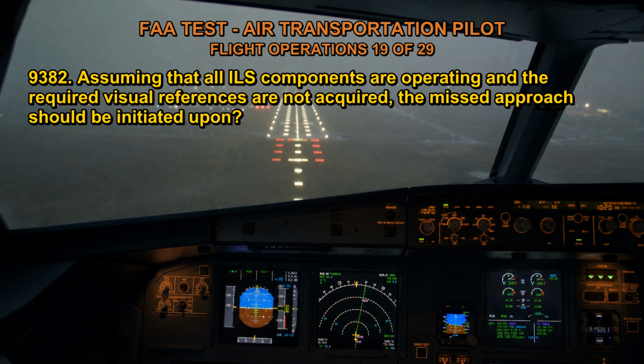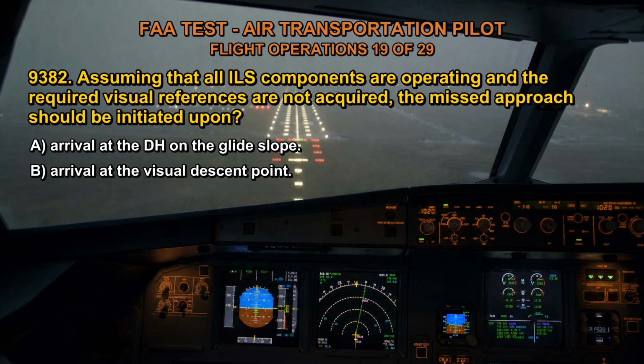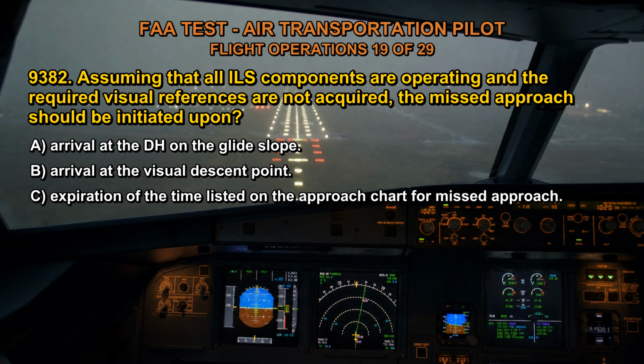9382. Assuming that all ILS components are operating and the required visual references are not acquired, the missed approach should be initiated upon A. Arrival at the DH on the glide slope. B. Arrival at the visual descent point. C. Expiration of the time listed on the approach chart for missed approach.